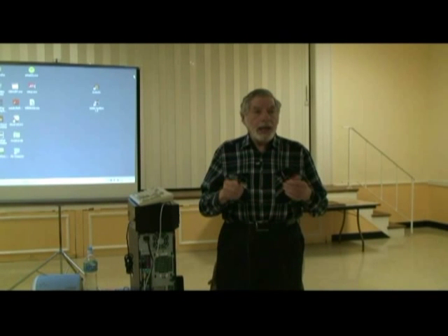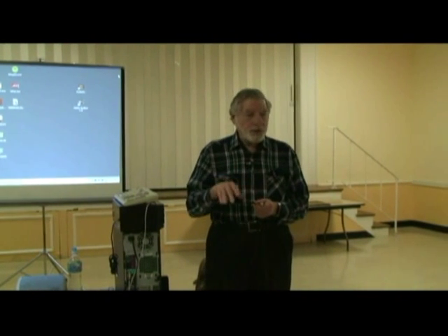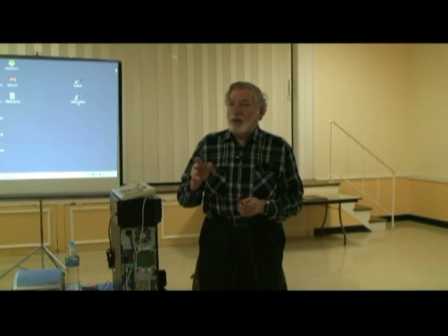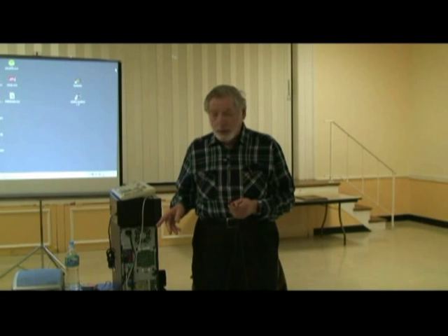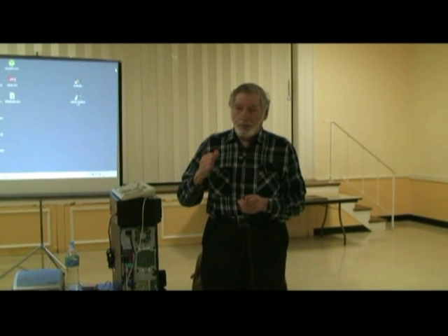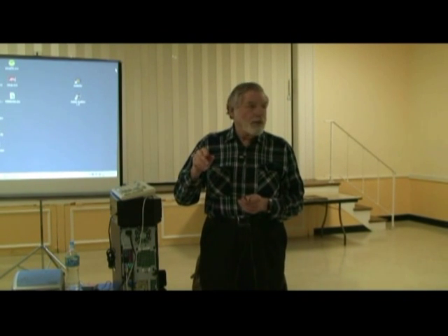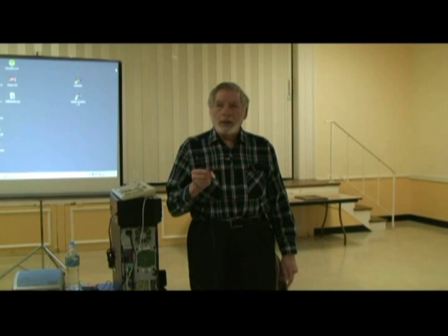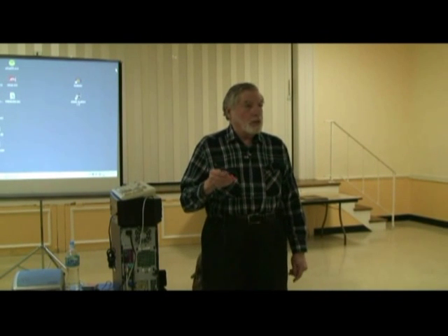Now, what I'm going to be doing tonight not only works for reel-to-reel tapes, which is what we are going to be working with transferring the library, it works on cassette decks, and even a turntable or phonograph, as long as you have a preamp, an amplifier giving you enough signal to go into your sound card, because most sound cards do not have a preamp in them to handle a signal coming from the magnetic head of a turntable. Turntables are a different kind of thing, but you can still do it. If you bought a turntable at a store that you can just plug into your amplifier, it doesn't need a preamp, and you can do the same thing and copy your records to a CD.